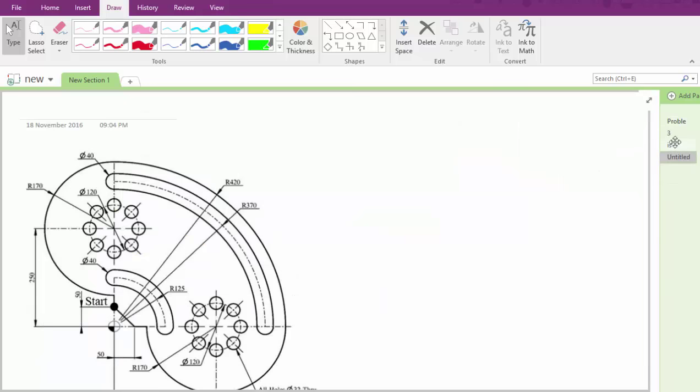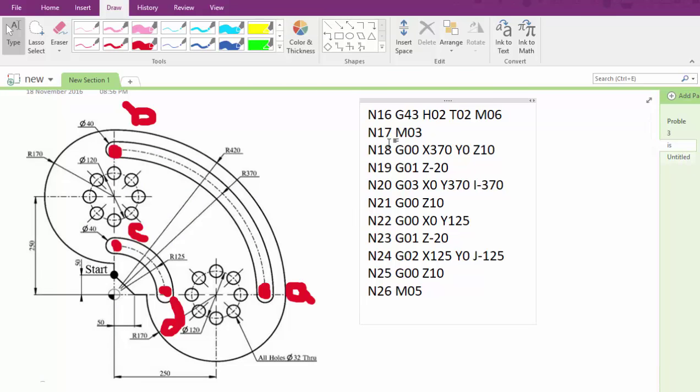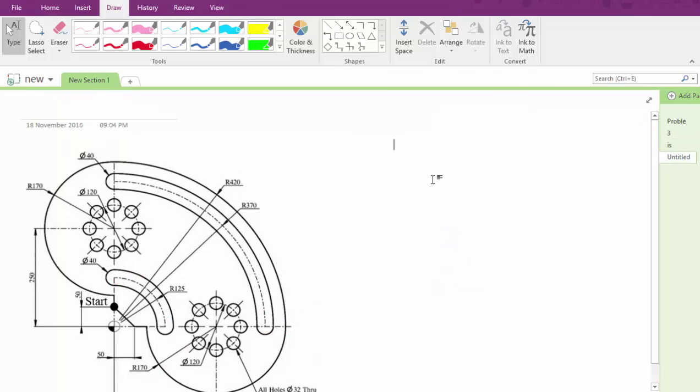Here we will start as finished at N26. Here we will start at N27 by changing the tool using T03 with the tool changing command M06. The tool offset adjustment command is G43 using H03 as we do. So now we have the tool mounted with the required tool offset, and now we are going to turn on the spindle using M03.